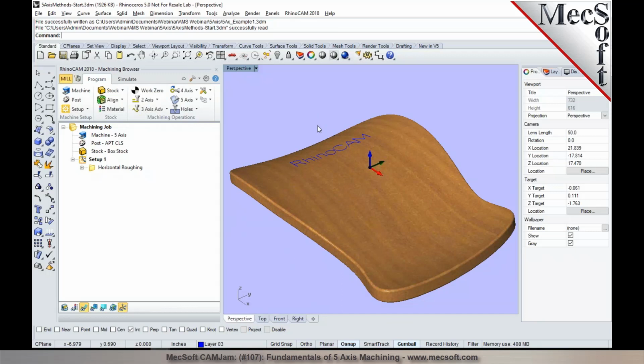So when we say continuous 5-axis or simultaneous 5-axis, what this refers to is you have 3 linear and 2 rotational axes, and all of these axes are moving or changing simultaneously as you're trying to machine along a surface. In the case of indexed machining, you are locking the 2 rotational axes to a given plane and machining, whereas in the case of simultaneous 5-axis, your 3 linear and the 2 rotational axes could be changing constantly.